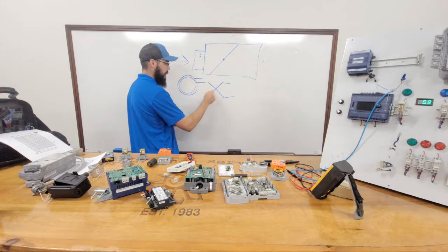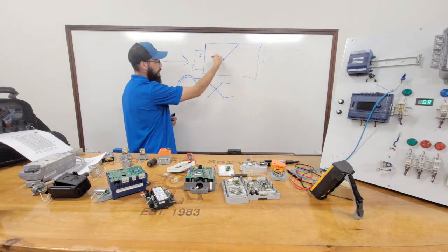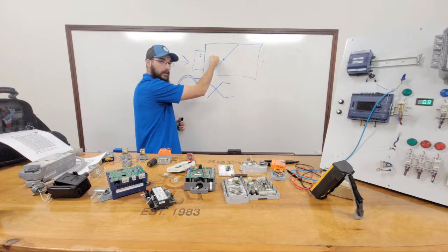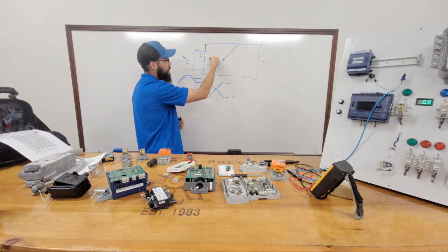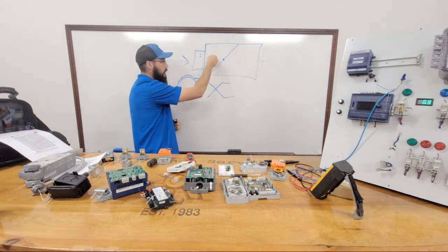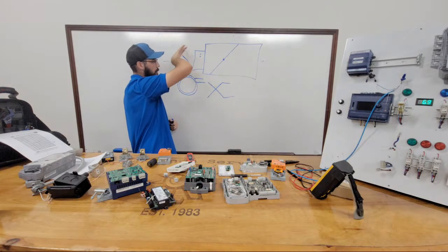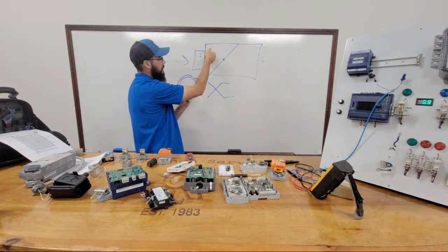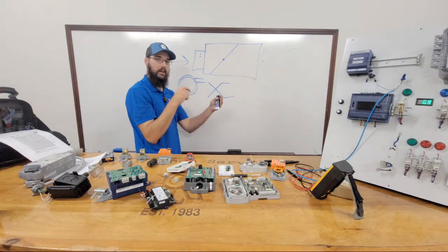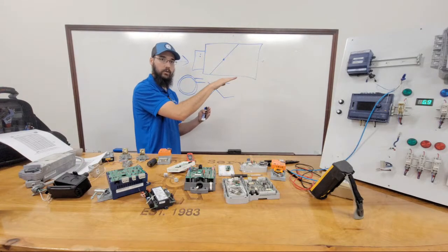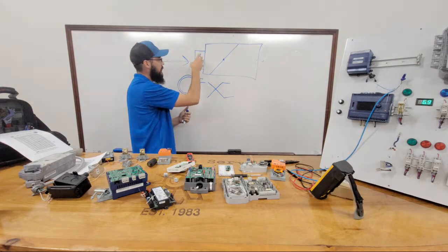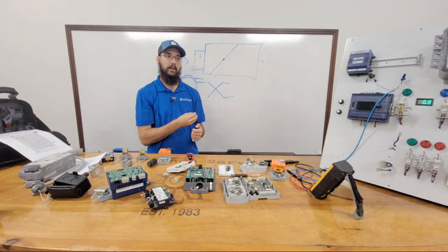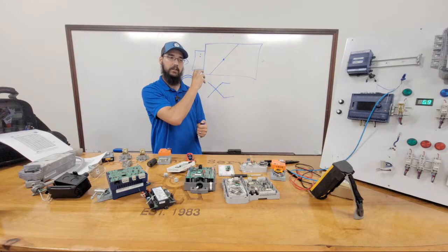The second ring, or the second port in the X, the tubes or the openings are going to be on the back side. They're going to be on the other end of the air. Those are your static ports. So the one on the front side is picking up not only the velocity, but also the duct static. The ones on the back side are picking up strictly the static. The velocity pressure is not shooting into the little holes. We're able to take those two pressures and the difference between them and chart them on a graph.